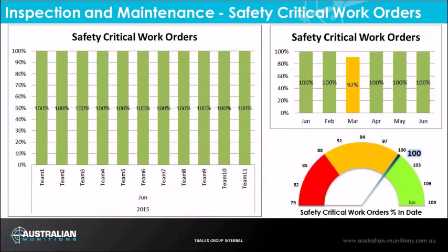Reoccurring maintenance actions are scheduled with the preventive maintenance module of a computerised maintenance management system. A subset of PMs are rated as safety critical. The determination process for a safety critical PM is made as part of a layers of protection analysis study. Safety critical PMs are scheduled preferentially during the creation of a maintenance schedule. This simple act of treating safety critical work orders favourably in the maintenance schedule process provides a higher level of assurance that these work orders are completed within the scheduled time period.